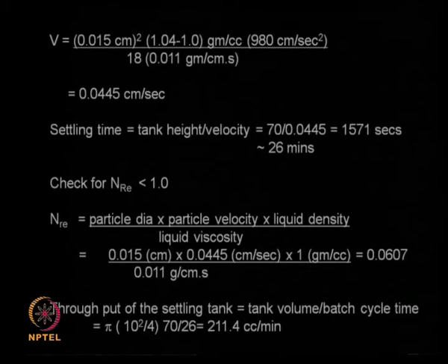So Stokes law depends upon dilute solutions, that means the solids that are settling down is not disturbing or impeding the solids that are present. So one solid may affect the movement of other solid either through collision or creating eddies or creating turbulence, then we cannot use the assumptions of Stokes law. That means if the concentration is very high we cannot use the Stokes law. If the velocities are very high in the form of turbulence, then again Stokes law is not very valid.